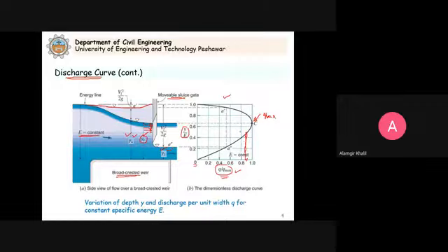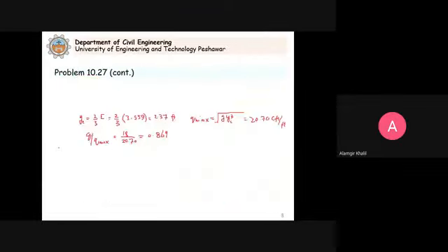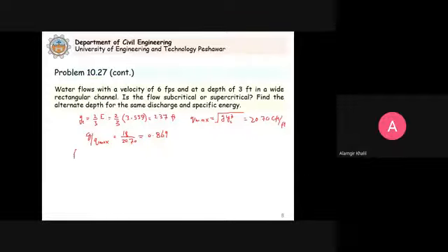And now from this figure, you read y by e. So you extend here horizontally. Now this is 0.4 and this is 0.6. So somewhere in the middle, this will be 0.5. So it is less than 0.5. Clear? So y by e is less than 0.5. From the figure, for this Q by Q maximum, this y by e is approximately 0.44.